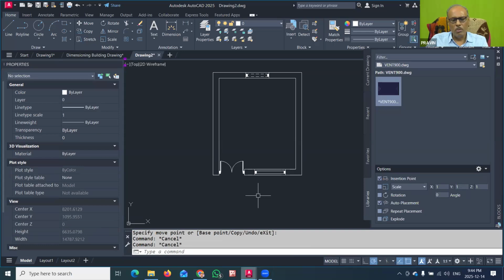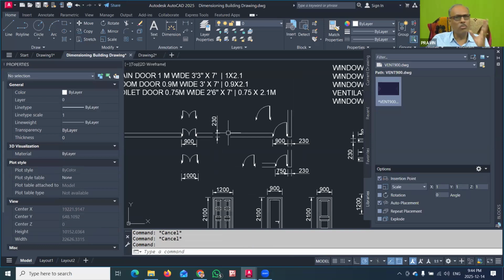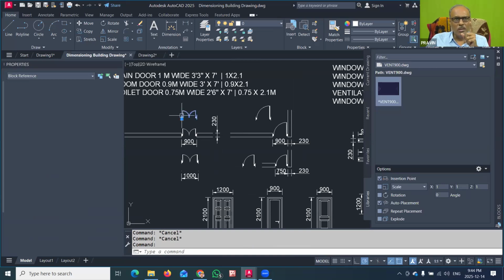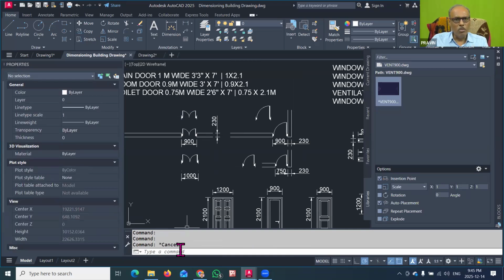The important thing you have to remember is to create the block. Whenever you create a block in any drawing, the first thing to remember is to create it on the 0 layer. Once you have created it, convert it using the block command. So it was converted to block. As soon as it is converted, type the W block command at the command line and convert this block into a universal block. Then you can save this universal block in a specific folder, so that on your laptop the folder is ready with all blocks.